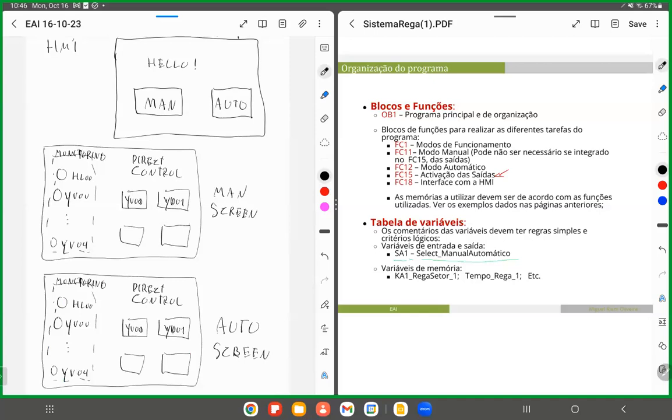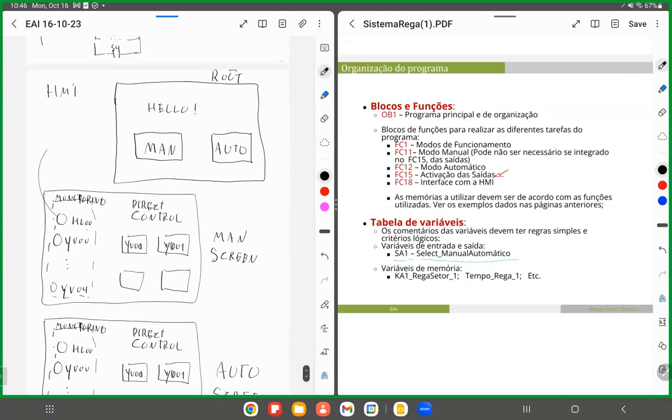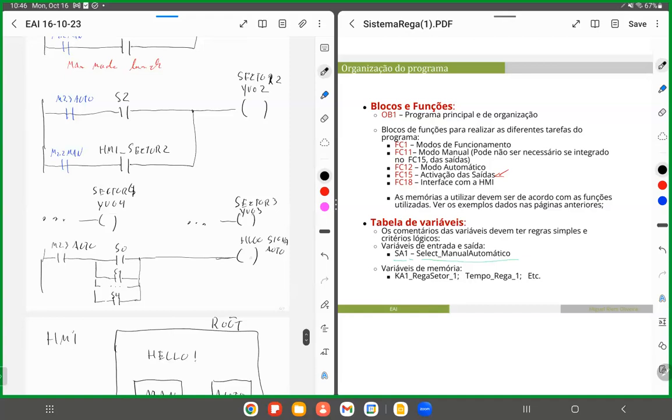We also have the monitoring. So typically what I do is I do the monitoring for manual and then I copy paste. So it's the same. Because this is not just copying the elements, the graphical elements, it's also copying the functionalities. So remember for this one, you will have to say something like go to animation, appearance animation, when variable, which is the variable that activates AGL00. It's called AGL00, signal auto, something like this.